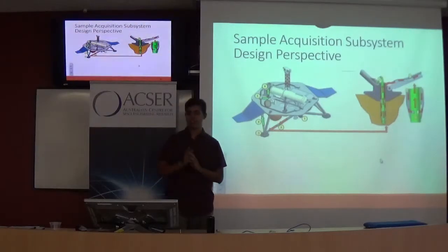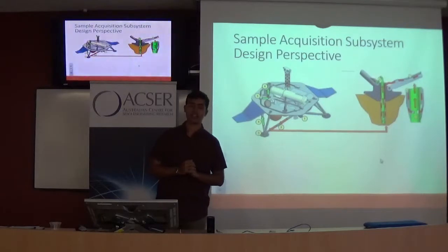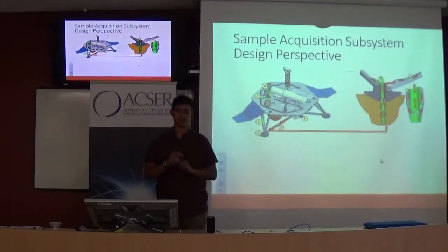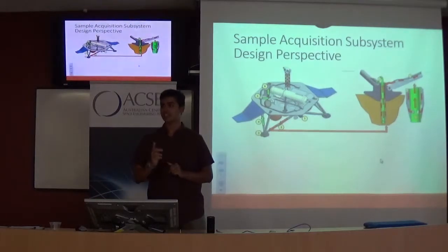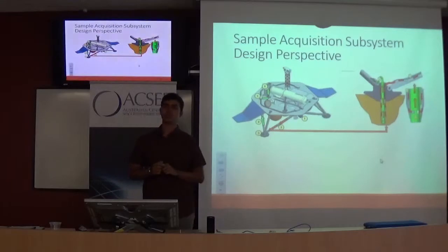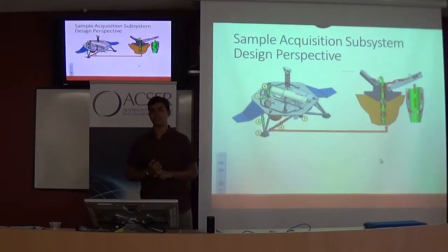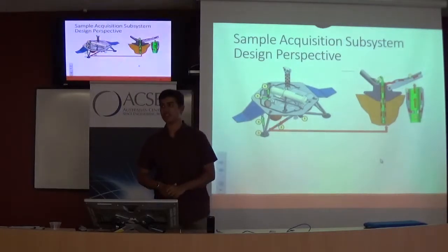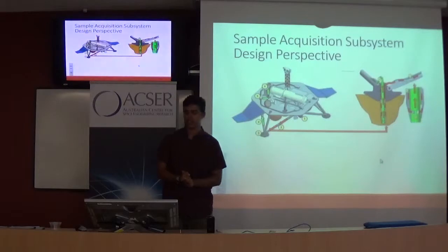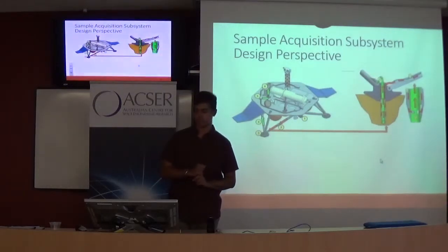So this particular design architecture, by no means being the final design of existing system being designed, but one of the candidate designs, actually uses that residual propellant. And that residual propellant is normally an inert gas, so it doesn't really react with the regolith, which is important. You don't want to use something that quickly reacts with your samples, and then your sample is basically useless. So it normally uses either helium or nitrogen, which is a common gas thruster.